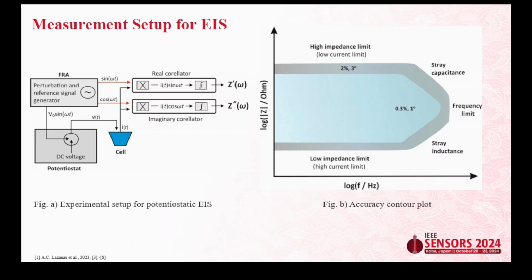We take the measurement, and if we measure the Bode plot, and both of us, like two different parties, get a response that comes into that blue zone, that is, your chi-square value is between 0.3 to 1%, that means that response can be repeatable, and the response that we are getting is actually the response of your system under probing, and not from some noise.